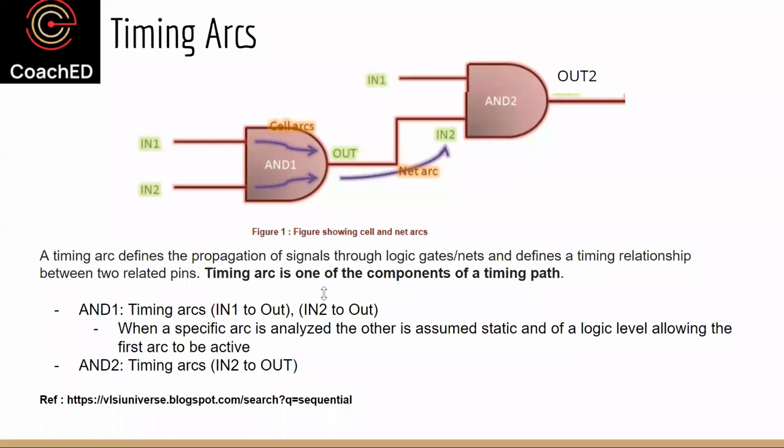Even in the industry, if there are, let's say, some silicon issues, or there are some specific cell level timing issues which we believe are not right, the way forward is to set up a simulation of just the small circuit that we are interested in analyzing, and we run a circuit simulation there. So circuit simulation is for accuracy.